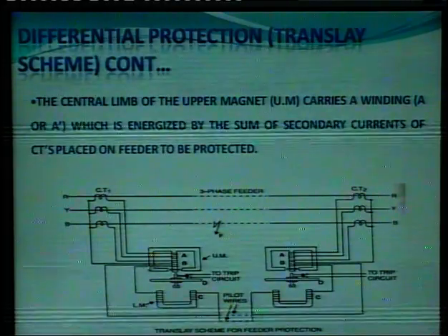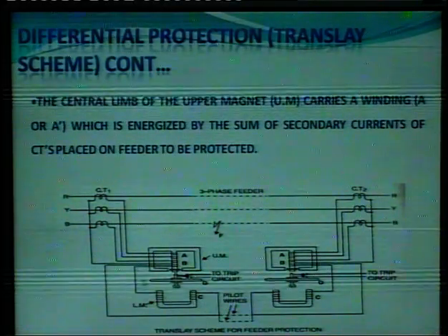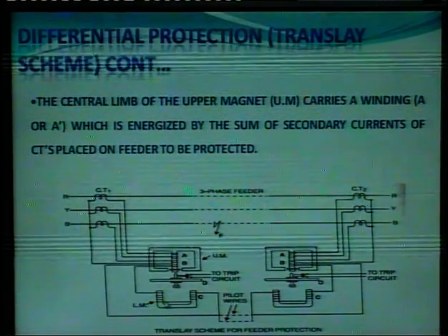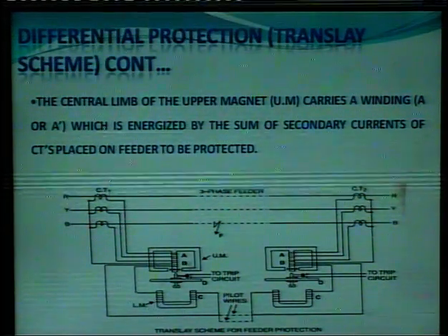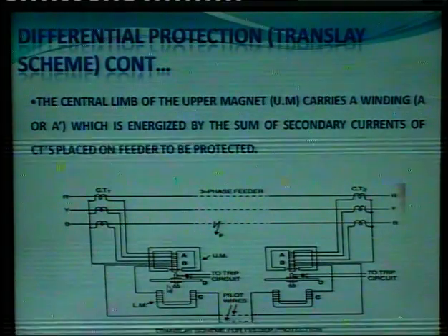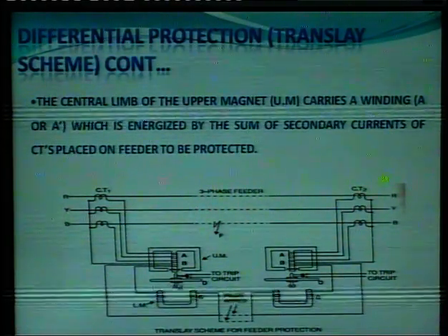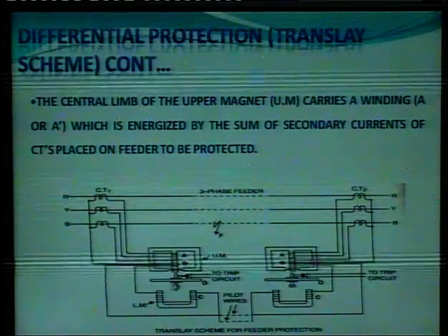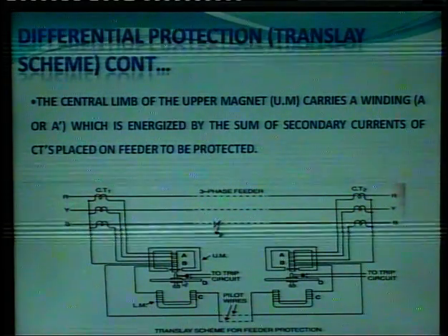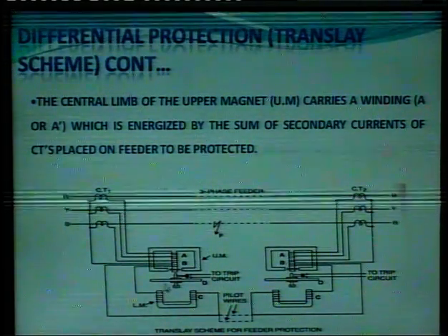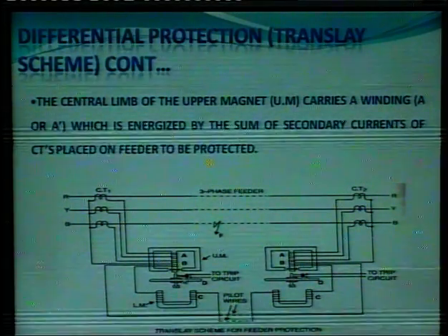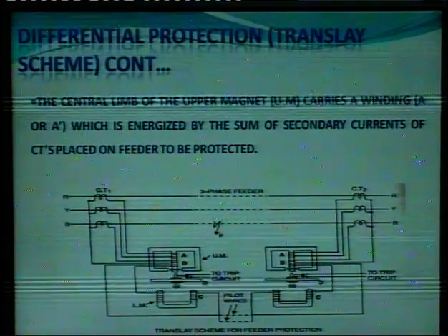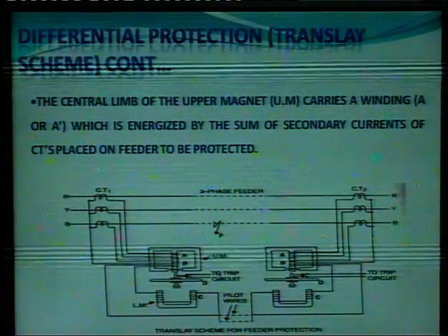So during the faulty condition, the currents in the two windings will not be equal. Therefore, this will provide the EMF in this disc, and this spindle will rotate, due to which the moving contact of the trip circuit gets closed.